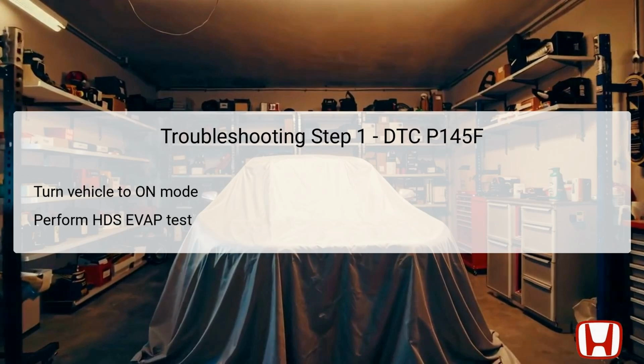This test will help determine if the module is working correctly or if it is causing issues with pressure readings. If the HDS indicates that the test result is not okay, this confirms that the fault has been duplicated, setting the stage for further diagnostic procedures. Understanding the outcomes from this step is essential.